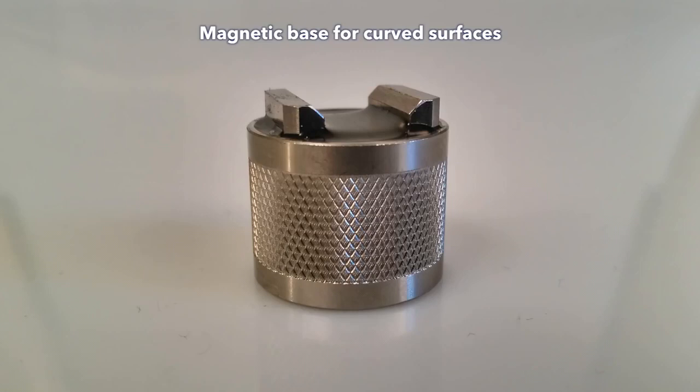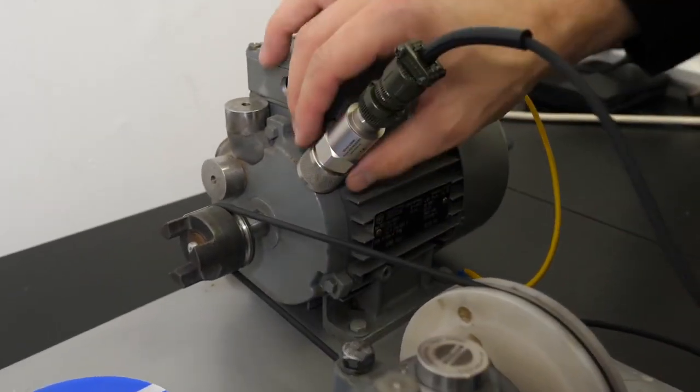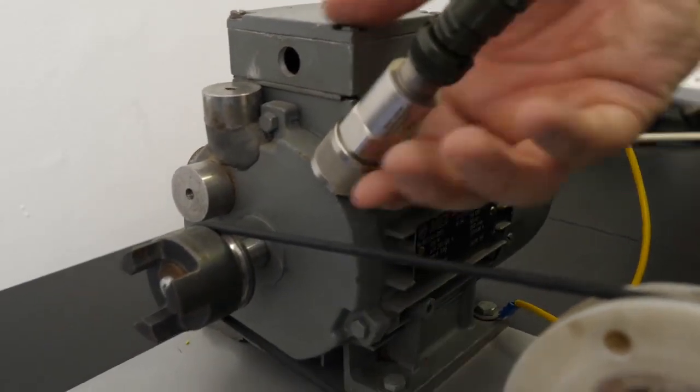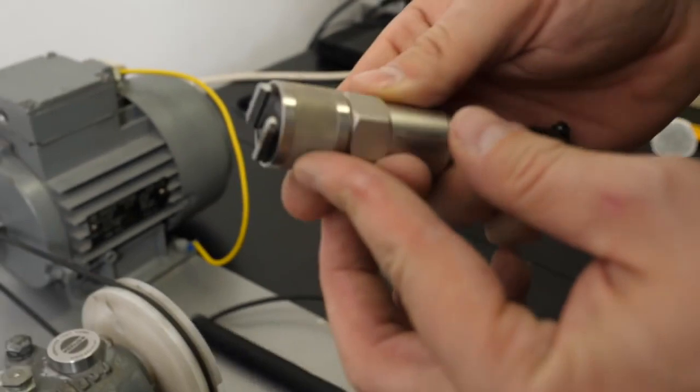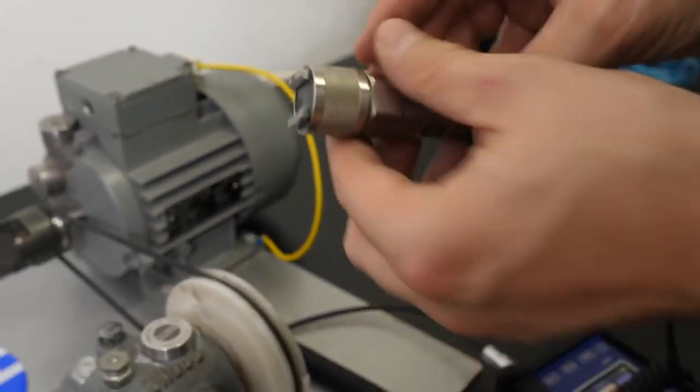If you don't want to glue measurement pads on your bearing housings, then you can use a magnetic base for curved surfaces. The disadvantage is that such a magnetic base has a little bit worse transmission of high-frequency vibrations. As you know from the first video, this means mostly bearing vibrations.